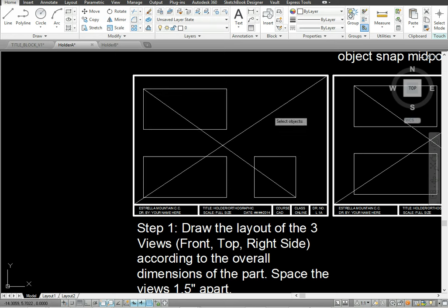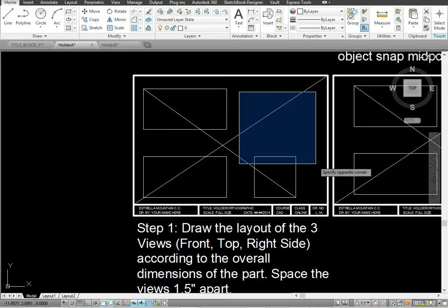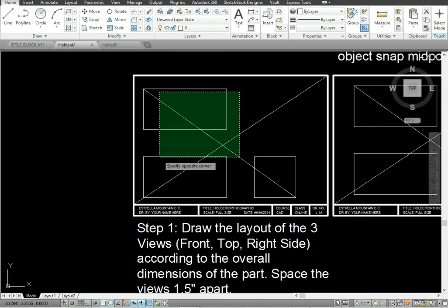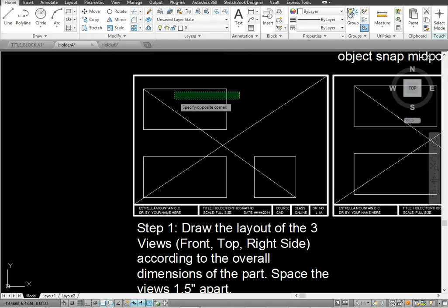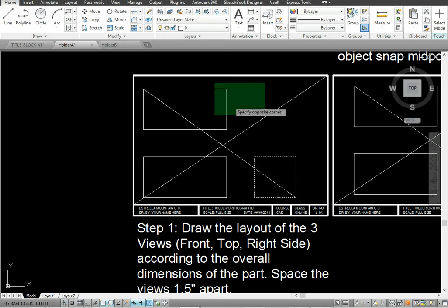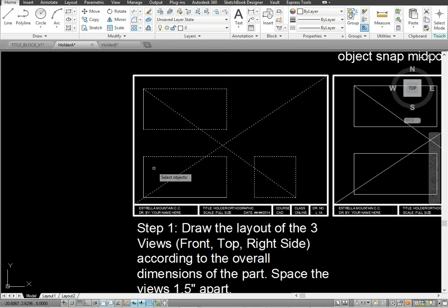So when you select objects, you will see blue or green. The pattern, solid on the perimeter or hidden or dashed on the perimeter, does different things. For blue, whatever's inside will be selected. For green, whatever's inside or crossing will be selected. You need to know the difference.